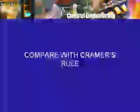Similarly for y2 and for y4. So, I will have 4 equations for y1, y2, y3, y4, in which the input signals x1 and x2 will also appear. Now, I can solve these 4 equations for the 4 non-input node signal unknowns y1, y2, y3, y4 using Cramer's rule or using some other technique of solving simultaneous linear equations.